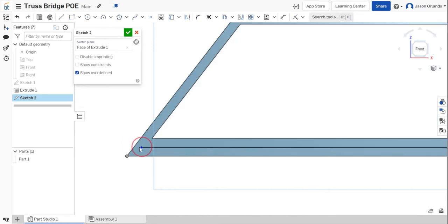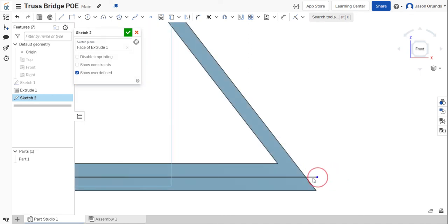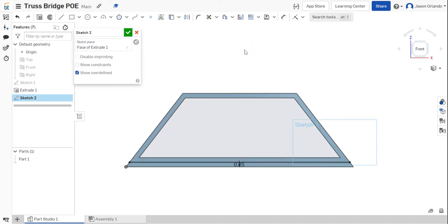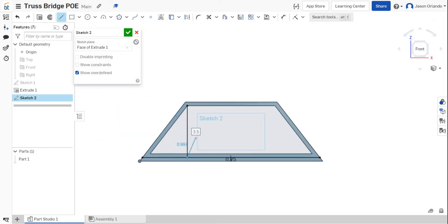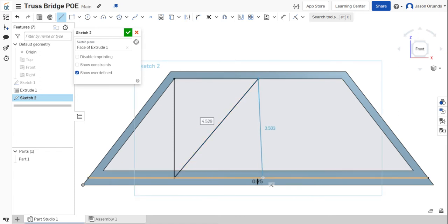And I'm going to click and drag this and then just let go of it when the line lights up, and it's going to be, the endpoints are going to be kind of stuck on that line, just so they're not floating or moving like that. Okay. I'm going to connect. This is basically trying to picture like the internal kind of pathways of our truss member. I'm going to find the midpoint. Let's go to here. Let's go straight down. I'm paying attention to those little icons that show up, and that should tell me when I'm horizontal or vertical or hitting midpoints or things like that.